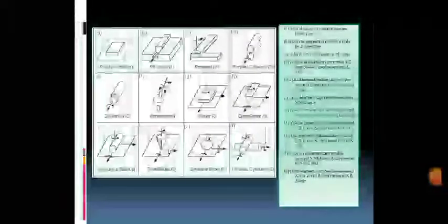So the degrees of freedom for this point slider will be equal to 5. Now next, picture K and picture L. Both pictures show only one motion that is not possible, and that motion is in the vertical direction. So the degrees of freedom for all these three examples, J, K and L, will be equal to 3.